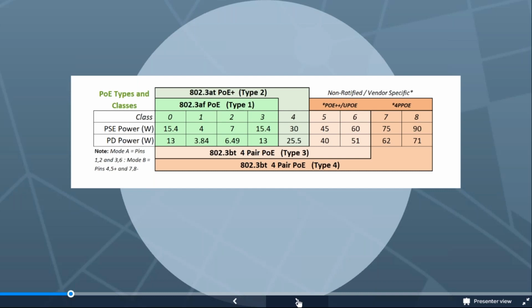Really, there's not a lot of devices any lower than that. Used to have some 15-volt and 18-volt, but really 24-volt is more of a common passive PoE. There is 48-volt PoE, and with the 802.3 AT standard, when we say 48 volts, it's really 56. Most 802.3 compliant devices will be able to handle the 56 volts, because typically you're doing longer cable runs.